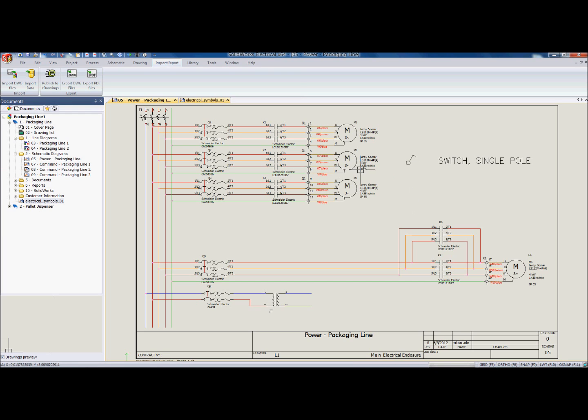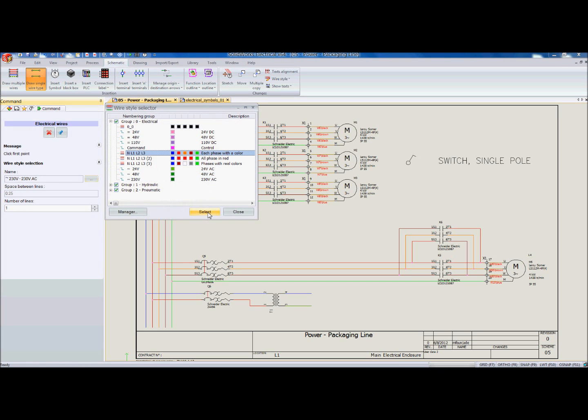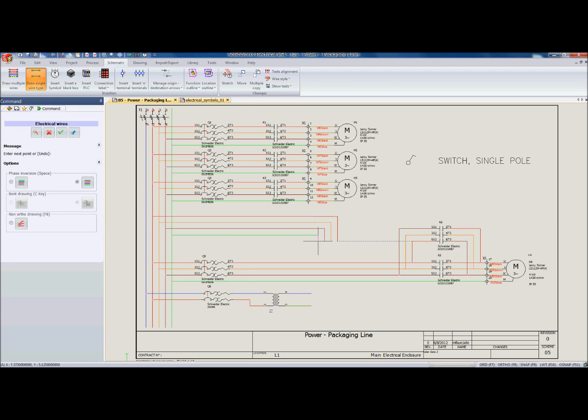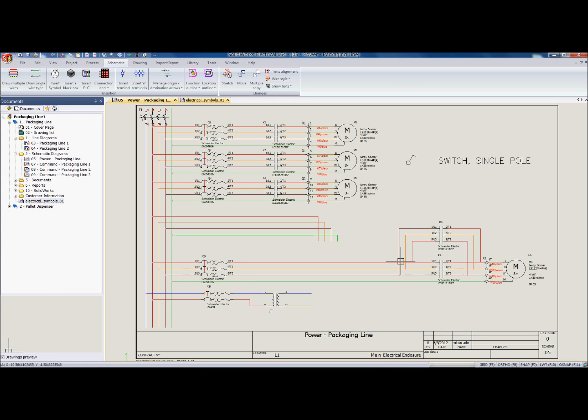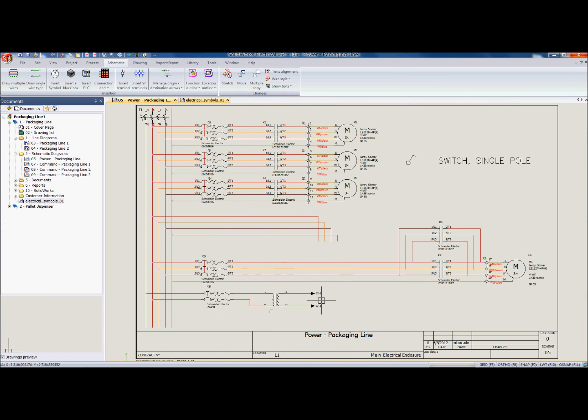Let's create a line in SolidWorks Electrical. A line can be easily created by simply selecting the default list, or you can make your own list of configurations. Then you can simply click and drag the line. As the line has an intelligent system, we can simply change the line type based on your needs. You can also control your multi-page references by simply clicking on Manage Origin and connecting them. With a few clicks, you can generate your page references without any human error.